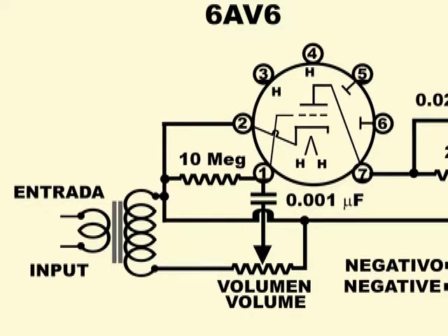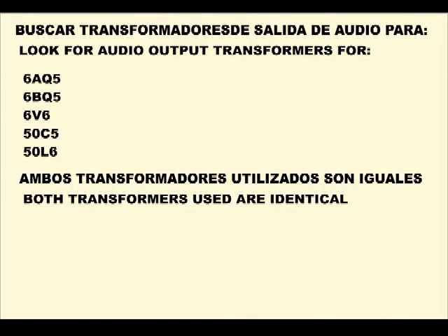On the other hand, we are also using a pair of identical transformers. One of them raises the input signal voltage before applying it to the triode grid, taking advantage of the fact that the grid practically does not load the signal at all and therefore does not weaken it.